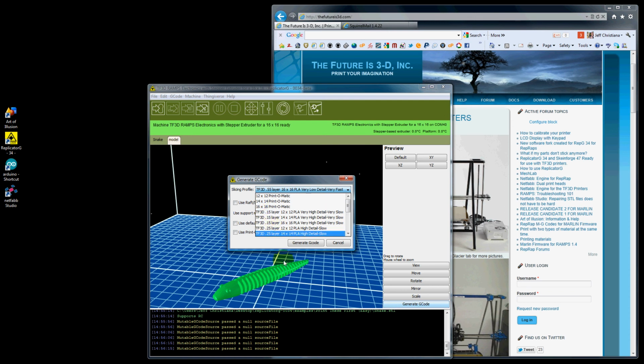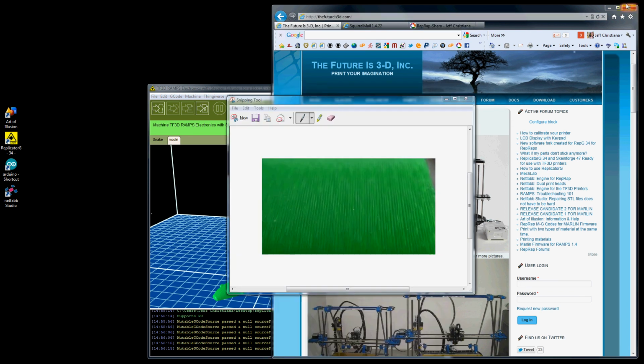Now I'm talking layer height. We're talking layer upon layer. Let me open up MS Paint here real quick. Here I've got a side view of one of our prints, and you can see, this is sideways, you can see here the layer height, you can see each individual layer. If you're going to print something at 0.15, your layers are going to be extremely close to each other.